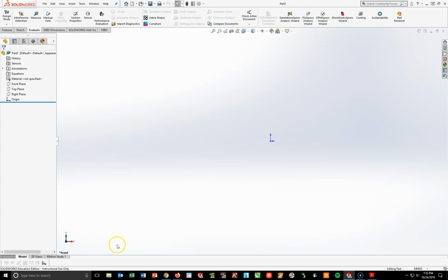And what this is going to do is give me a blank drawing environment. This is the drawing environment here for SolidWorks. At the center of it is our origin. That is the 000 mark of space. That's the X, Y, and Z 0 mark. Over here to the left, again, is called the design tree. And when we start a new part, we need to reference the design tree to figure out which plane I'm going to start from.